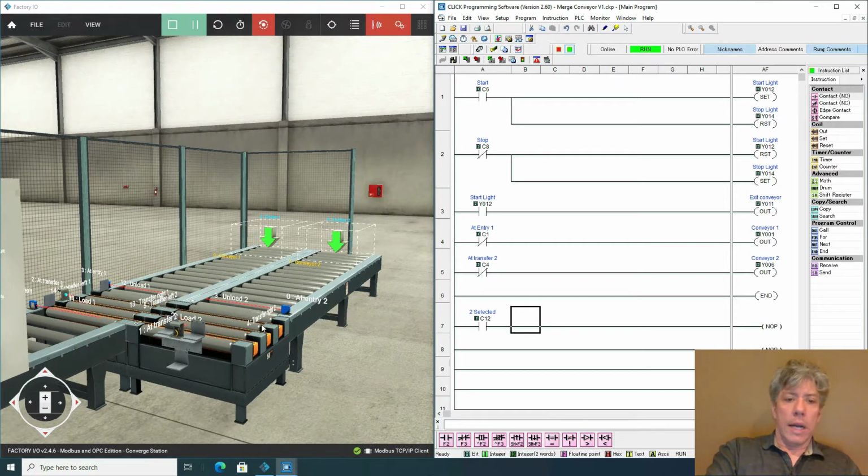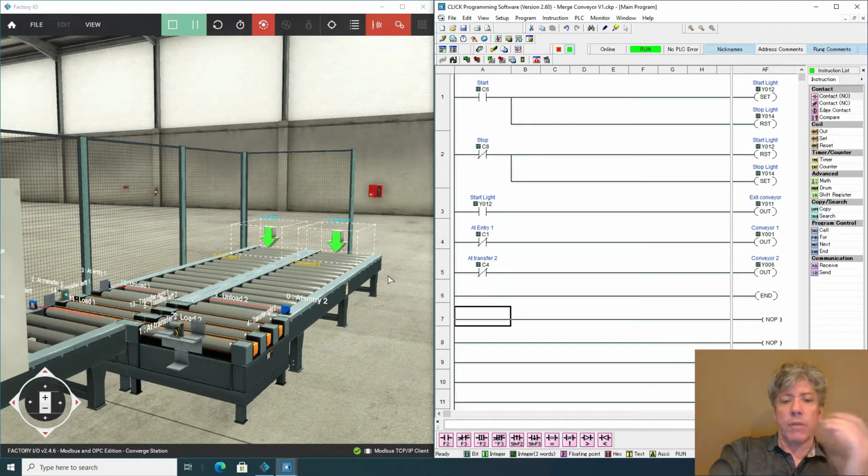before I could actually bring it in and make it go, right? You know, maybe that's not such a good idea, because part of the sequence is going to be getting the pallet from the conveyor onto the transfer conveyor. So how about if instead of doing that, I hold off on deciding? Really, what I want to do is start the sequence by getting something in place, kind of pause the sequence, and then when it's actually conveyor 2's turn, move it over and let it continue on. So I think what I'll do is make this part of the sequence so that I can solve the problem of getting the pallet from conveyor 2 onto transfer conveyor 2.